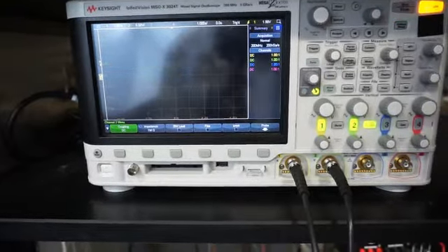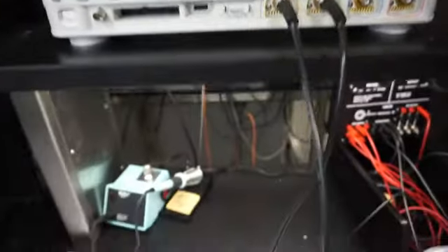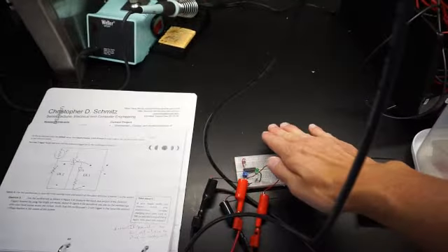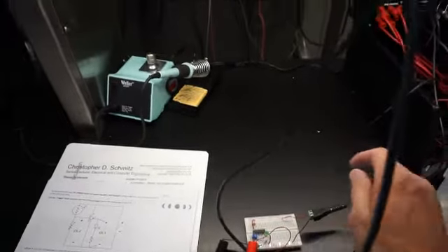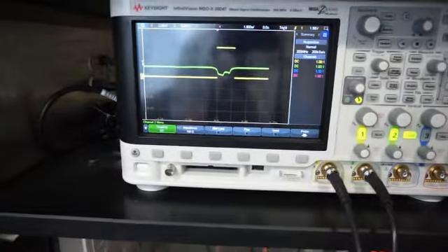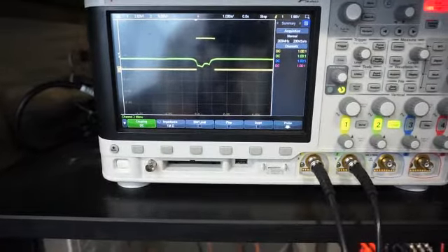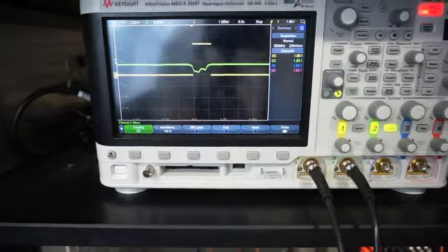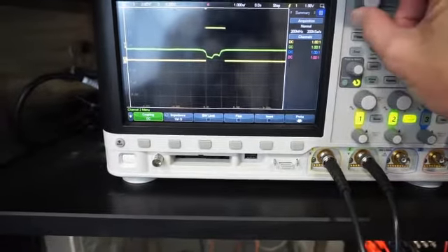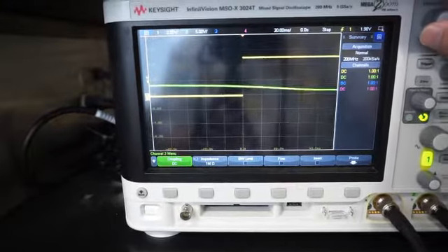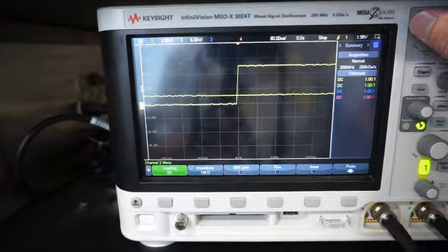Press the single sweep button on the upper right of your scope, then shadow your cloud detector circuit to collect a block of time-varying voltage signal. You can use the horizontal axis adjustment to zoom in and see that the scope gathered data before and after the voltage crossed the 2-volt trigger setting.